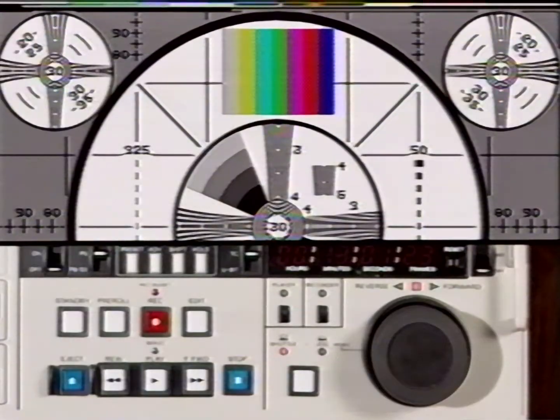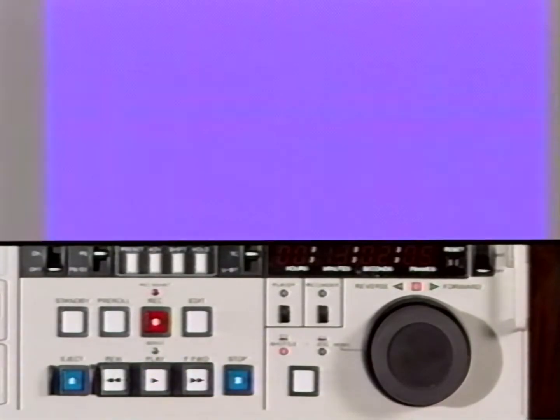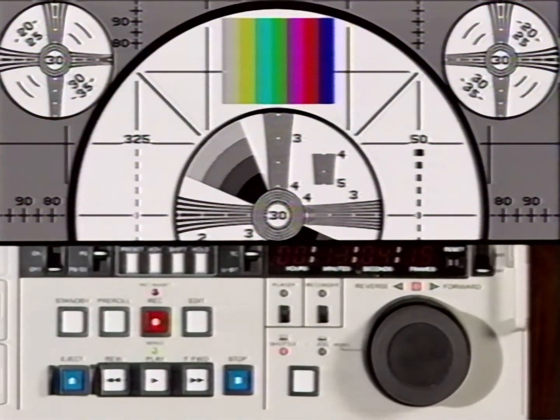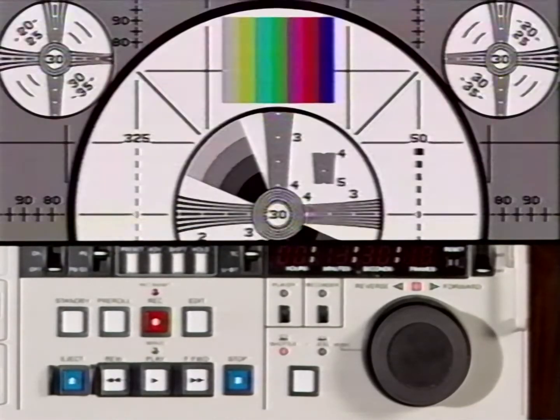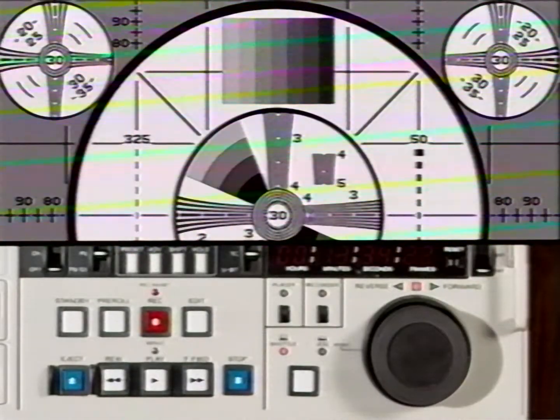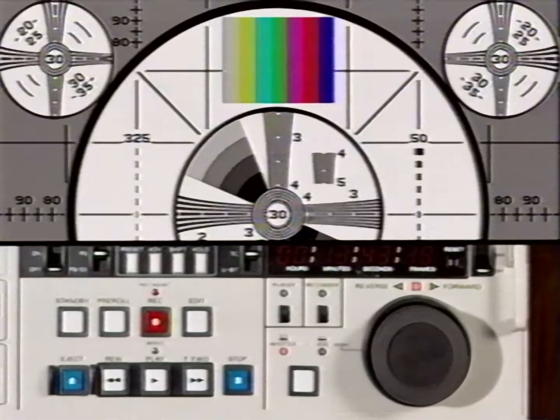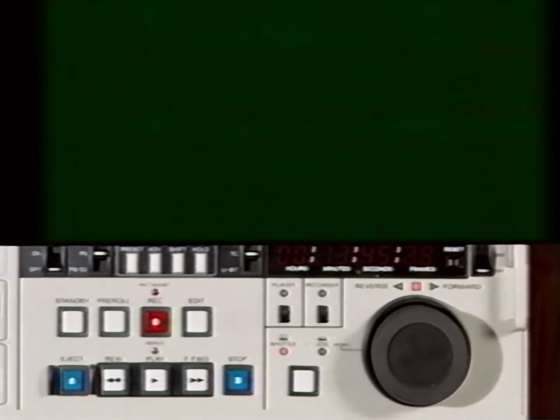Capstan free speed. When the capstan free speed is adjusted correctly, the tape runs smoothly and there are no observable problems. The servo lock light, located directly below the red record switch, is lit. The servo lock light is difficult to see in this tape. It is easier to see the light go off. It blinks on and off with occasional signal breakup and stays off with more extreme misadjustment.